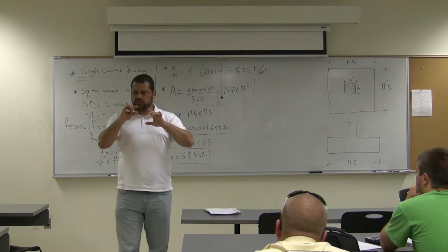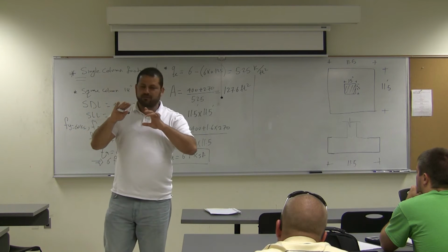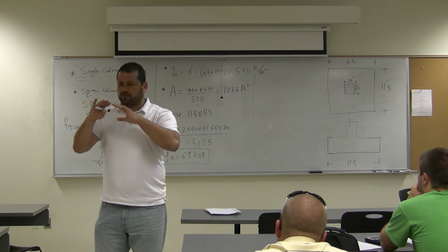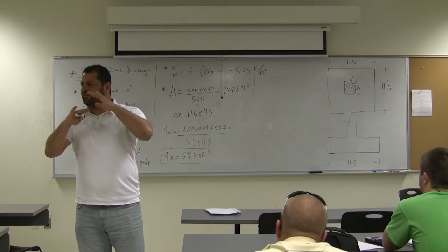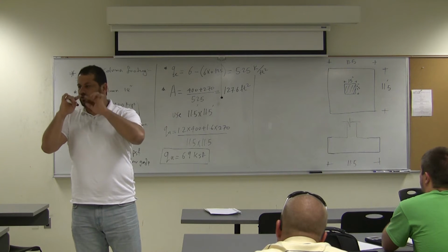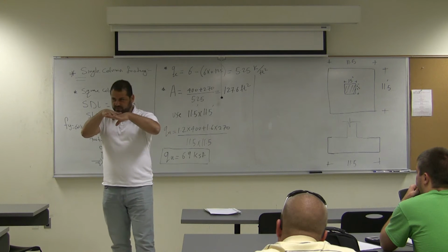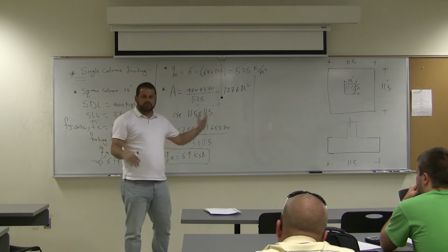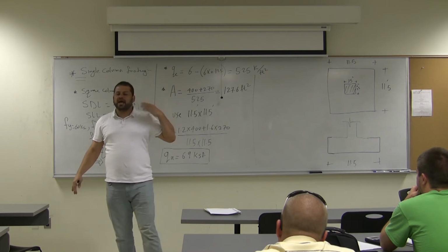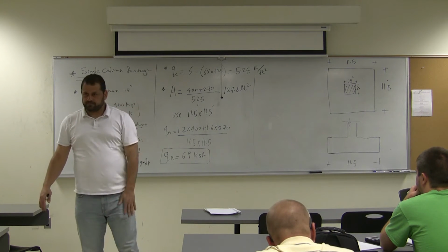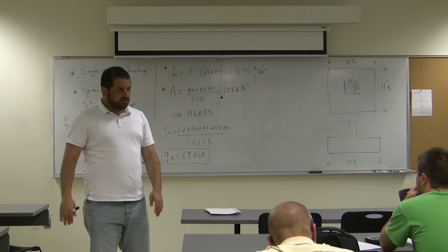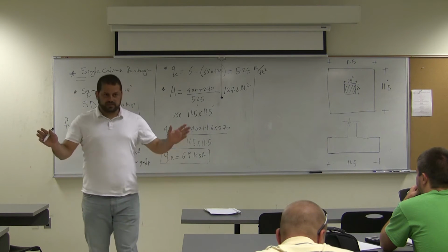If you take 1 inch, it will be good, because you may say the top layer will control, but how about taking an effective D between the two? They both work together because they are tied together. So 1 more inch will be enough. So usually the final depth equals D plus 4. That's a good assumption.